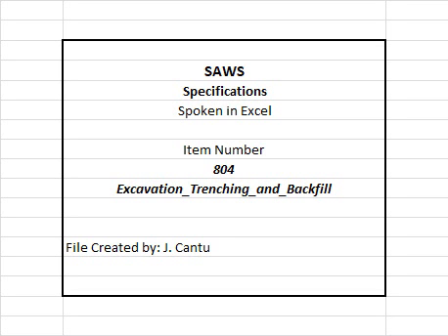2. Backfilling for pipelines is divided into three separate zones. A. Bedding, the material in the trench bottom in direct contact with the bottom of the pipe. B. Initial backfill, is defined as backfill having a thickness in its compacted state from the surface of the bedding to a point 1 foot above the top of the pipe. C. Secondary backfill, the backfill zone extending from the initial backfill surface to the top of the trench. D. Materials and placement for each of the zones shall be as described herein.